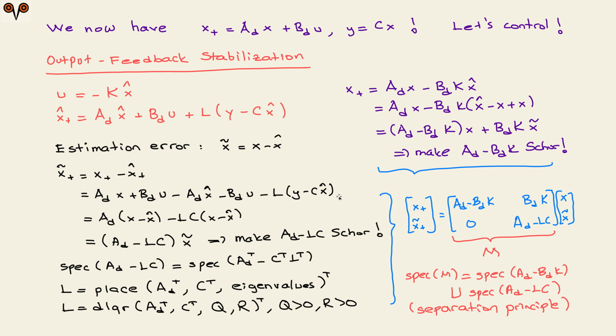When your system state X is not available for feedback purposes, it is not measurable, so you need to do your design with Y. Quite similar to the continuous time, we have this discrete time Luenberger observer. The first part mimics the system, with X replaced with X hat because X is not available. I cannot use it for control. This is my control architecture that I need to implement. And Luenberger gain L, Y, measurable output, minus C X hat.